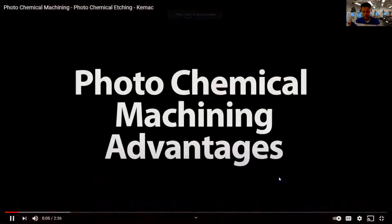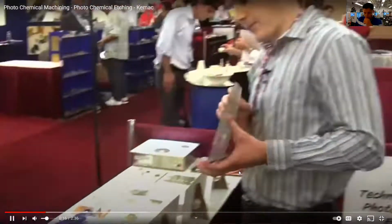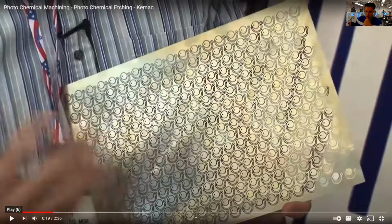So the main benefits of photochemical machining over, say, a laser or an EDM process: it's all thin material, and we don't have any burrs or heat affected zones. The other advantage is when you have, say, a tiny part, we can lay out that part on this entire sheet. So look at how many parts they have on that sheet right there.